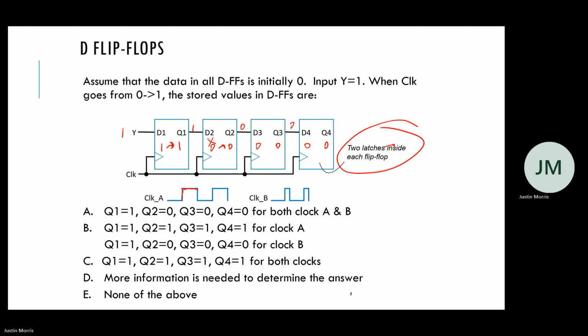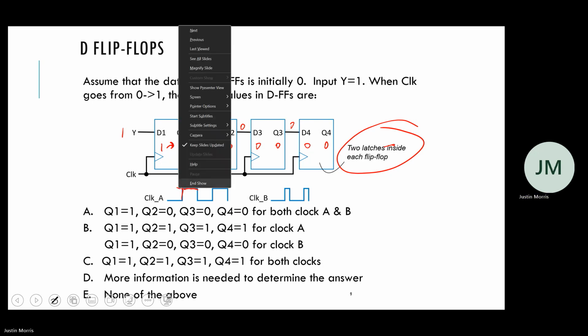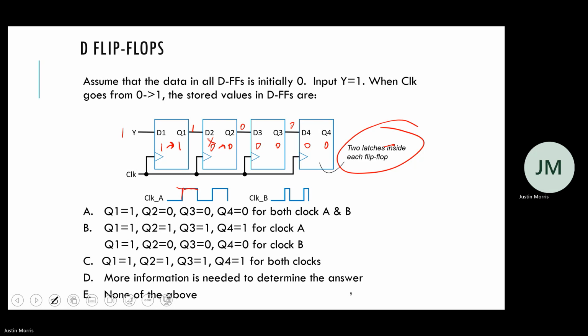It's stuck, right? So now we can have looser timing with our clocks, and it makes timing much more simple. Because we just need to make sure that before this positive edge, we're stable, and then a little bit after it, to make sure that the first latch is completely disabled, we keep it stable for a little bit too.